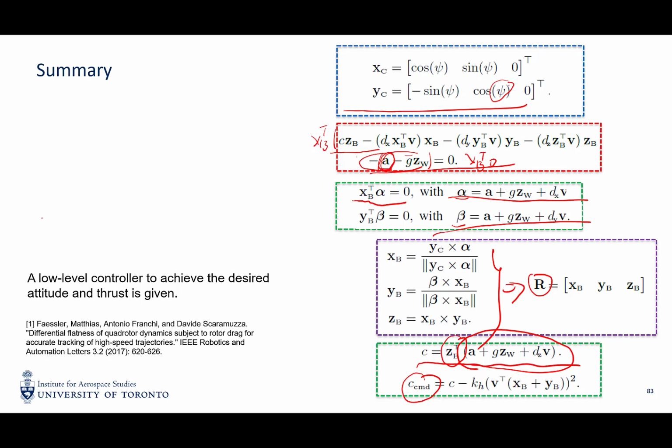If you have a trajectory, and you're away from the trajectory, then you need to design your acceleration, basically the A here, based on the error. So this is your job to design the A. And if you get A, put it in this alpha and beta, you should get R and C. All lower level controllers are already constructed for you, so you can just use that.